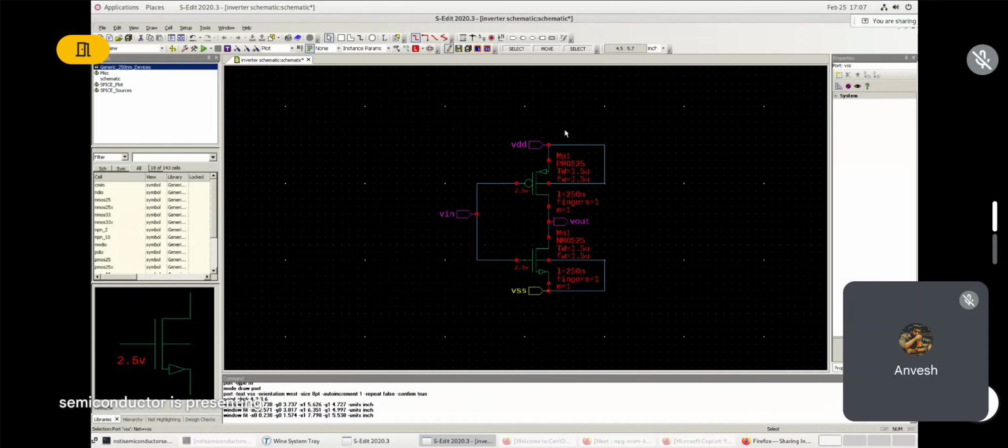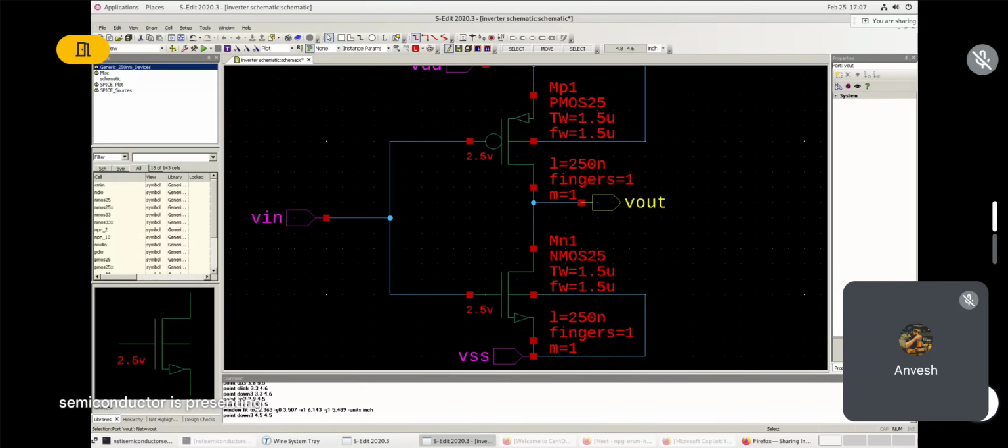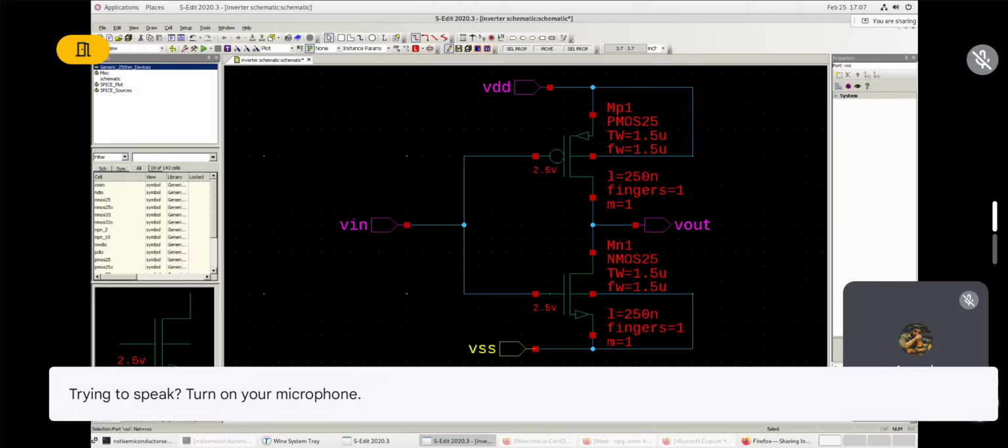Now, what I will do is Control S. And here, you should not directly connect to the wire. You have to extend this using a wire so that it will not get short circuited. To prevent the short circuit, I will add the extra wire. So I will click on this. Once yellow color appears, click on the center mouse button and drag it. If you click on the center mouse button and drag it, it can be elaborated. Similarly here. Now you click on the home and I will do control save. Now the design is ready.